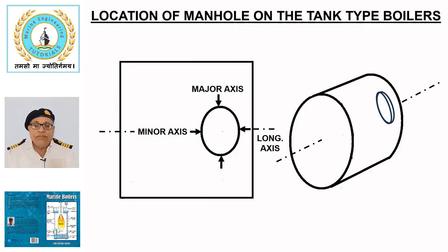Contrary to this, if the manhole can be located on the disc end, it can take any position, as the longitudinal stress is applicable on the disc end, which is just half of the circumferential stress.